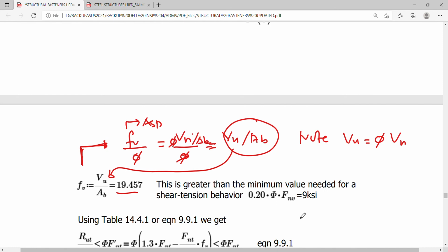And this is 20%. So always 20% of phi F and B. In our interaction diagram for a beam column, normally this 20% is the basis for an interaction to be expected, or else there must be some additional reduction factor to be inputted in your interaction equation to make sure that your combined effect will behave accordingly.